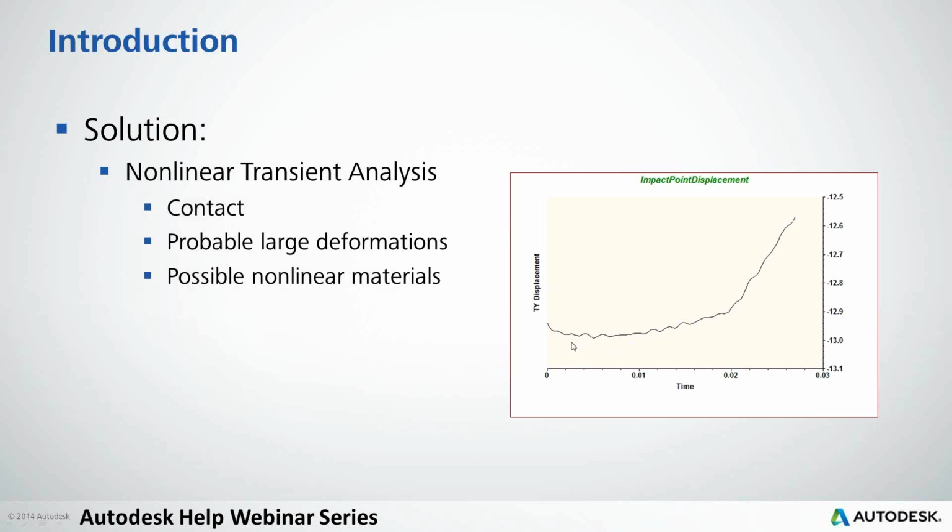And most of the stresses and the interest are going to happen at the impact point, but occasionally this particular one doesn't rotate, but often when you do a drop test, it'll hit one corner, and that corner will rebound, and then another corner will come in, so you'll have another point that starts up here and moves down and hits on its own. So you can get some complicated, large deformation behavior out of it.